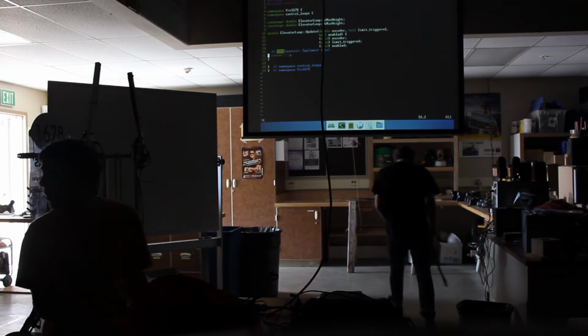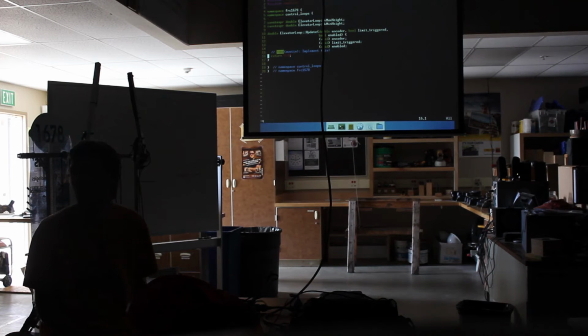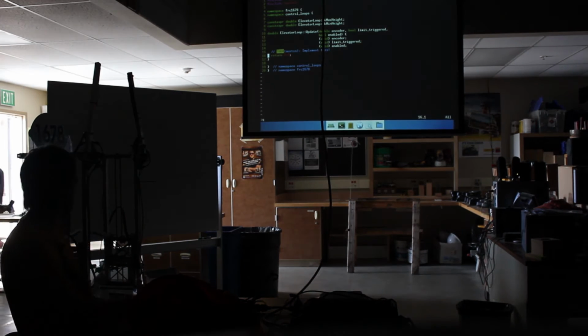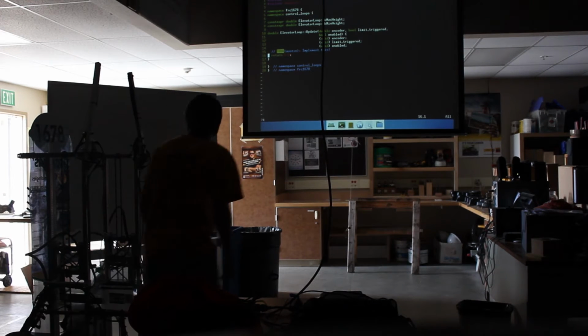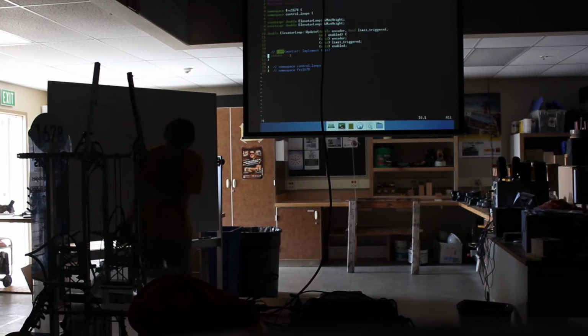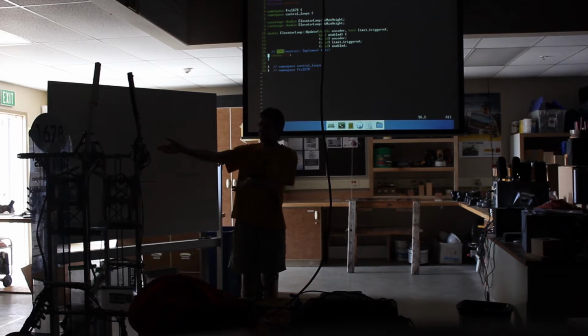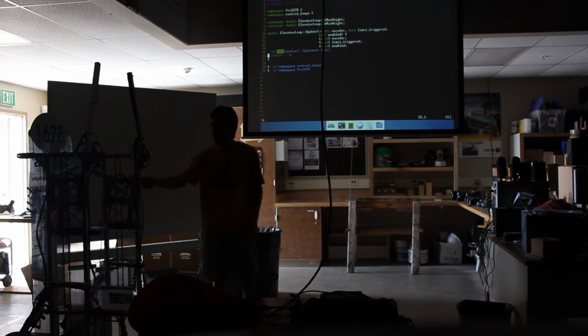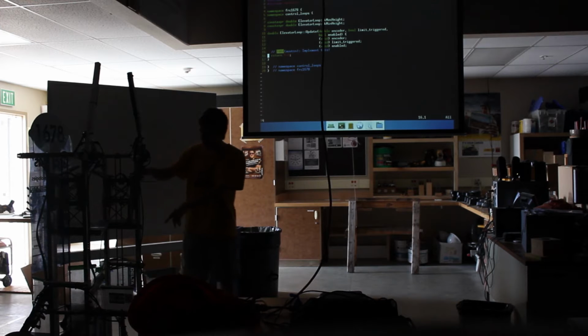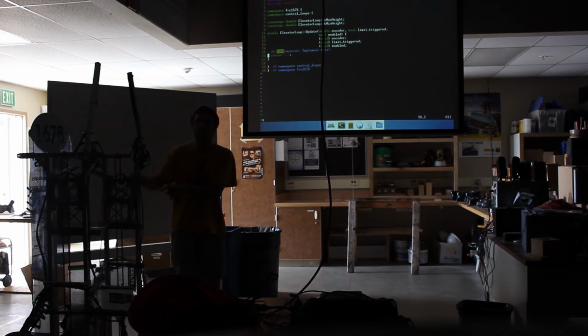So can you give it like a step input for a different position we want it to go to? We can do that. I mean, let me describe the problem we need to solve. So when we start this elevator out, someone's going to turn the robot on. It's going to be at some position. The encoder is going to read 0, but it's not going to actually be at 0. So what we need to do at the beginning is we need to implement a homing procedure.